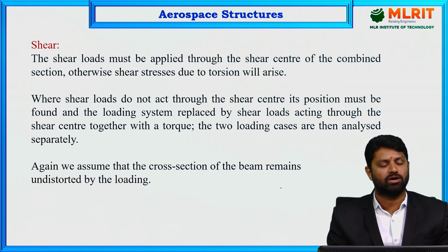Now coming to the shear loads, as we discussed about the shear center, the shear loads must be applied through the shear center of the combined section, otherwise shear stresses due to torsion will also arise. We have discussed the shear center, which is a point in the cross section about which there exists no torsion.